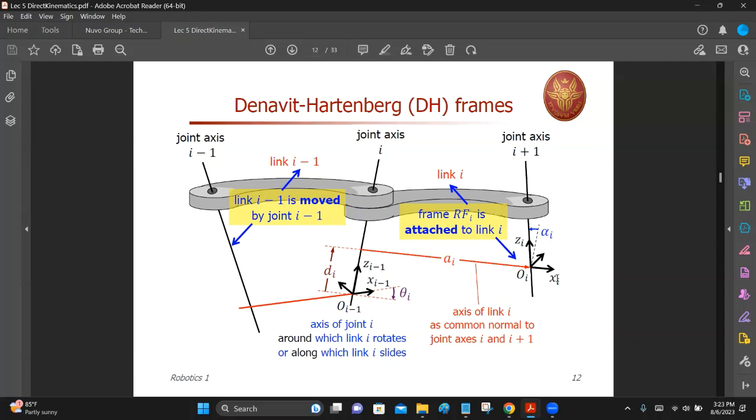So now it boils down to one single question. What is the mathematical description for the first screw operation and for the second screw operation? If you know how to write a screw operation, it is just a repetition of that here. First, you take the joint parameters. Later, you take the link parameters. The two screw operations.